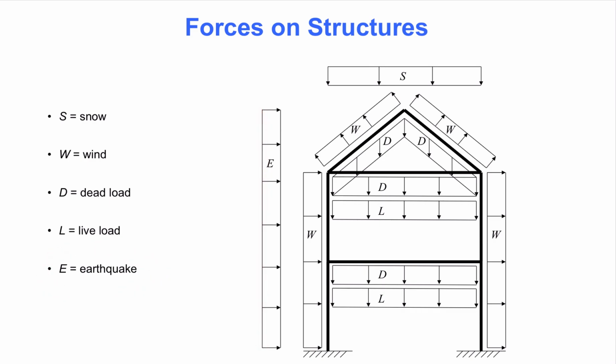However, a simplified approach in the building code is to consider the effect of an earthquake as static lateral load on the structure. Newton's second law suggests that that load is proportional to the mass of the building. Although many factors play into the calculations, it may not be unreasonable to say that this simplified earthquake load is 25 to 50% of the building's weight.